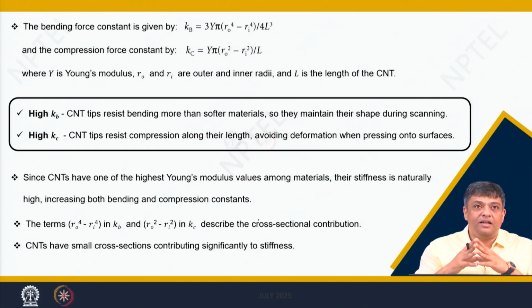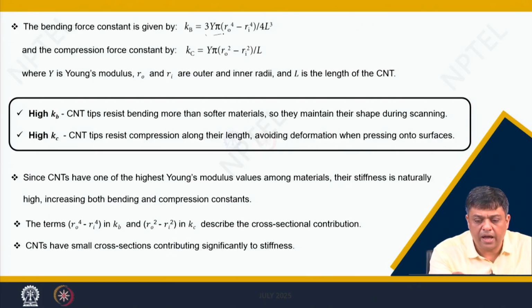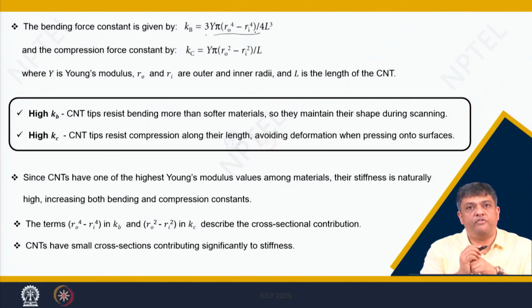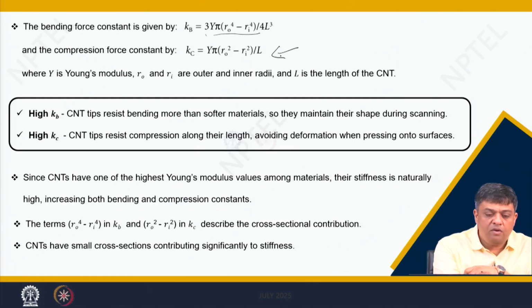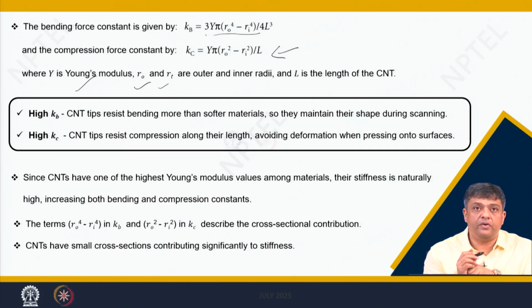And the bending force, if you want to understand the compressional forces and the bending forces which can act on the tip, the bending force constant is given by Kb = 3Y I (r0^4 - ri^4) / 4L^3, and the compressional force constant is given by Kc, where Y is the Young's modulus, r0 and ri are the outer and inner radii respectively, and L is the length of the CNT.